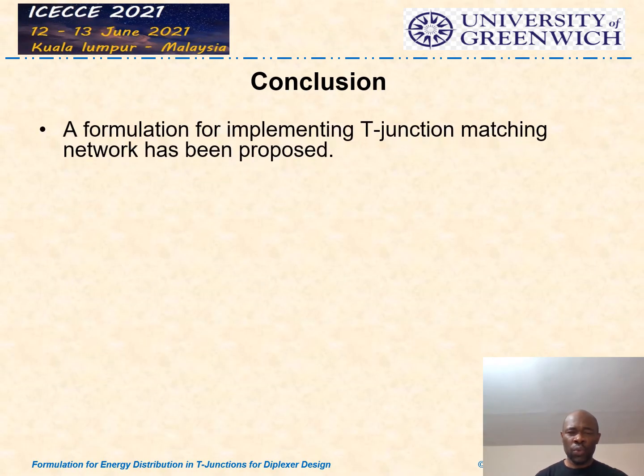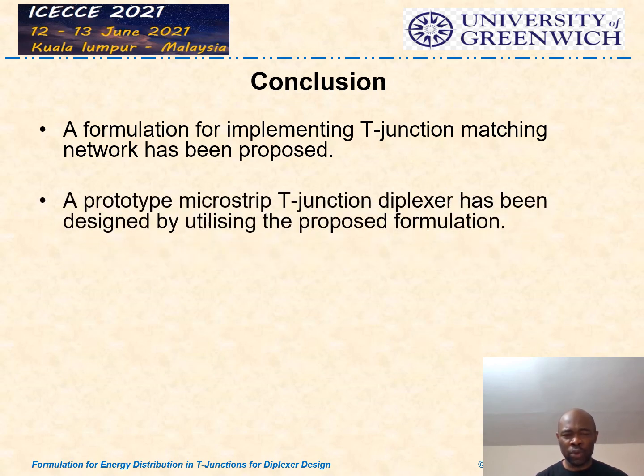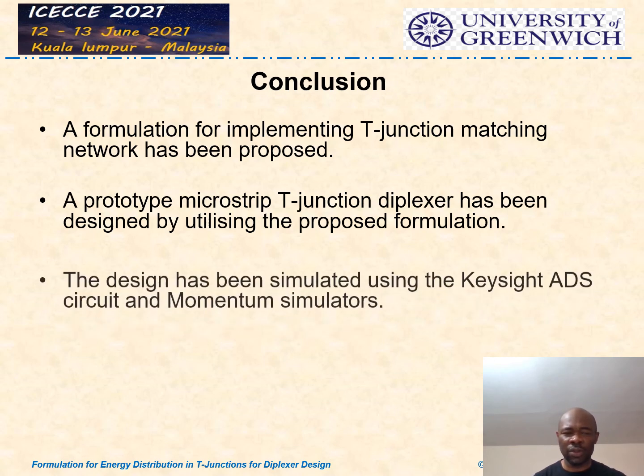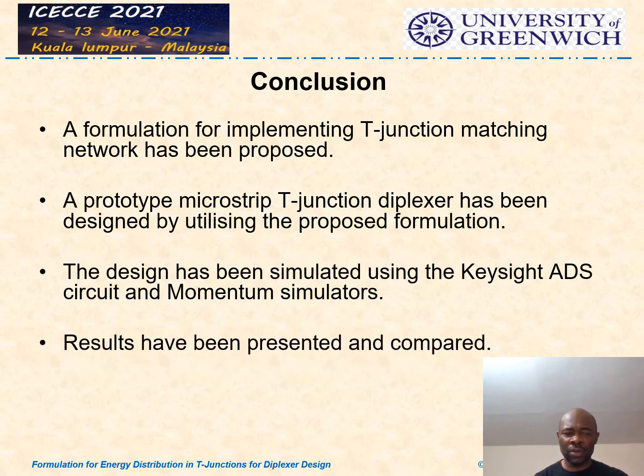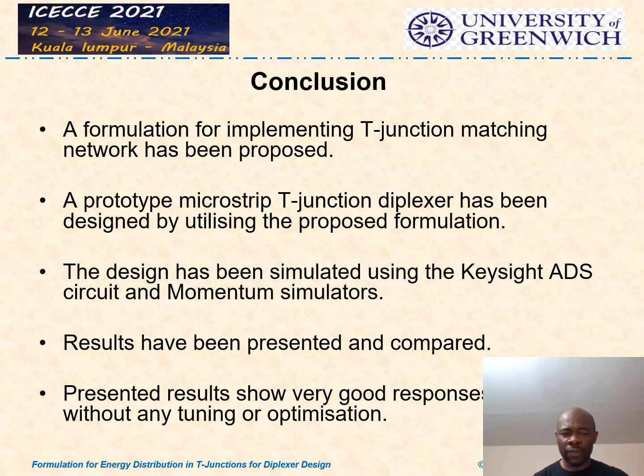In conclusion, we have been able to present a formulation that will help achieve a diplexer without going through tuning and optimization. The prototype diplexer that we presented shows good results. We did not use any tuning nor optimization, just formulation, to achieve these results. This simulation was done using ADS circuit for the circuit, and ADS Momentum for the microstrip layout. We presented our results and made comparisons, and it shows that this work is valid.